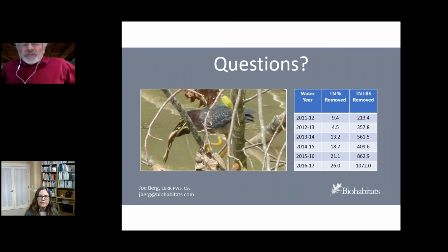Well, it's definitely experimental, but I think we know enough about wetland treatment to have confidence that when we're looking at a 1 square mile drainage area and a 25-acre treatment area, we should be able to get up into the 50s, 50% removal.